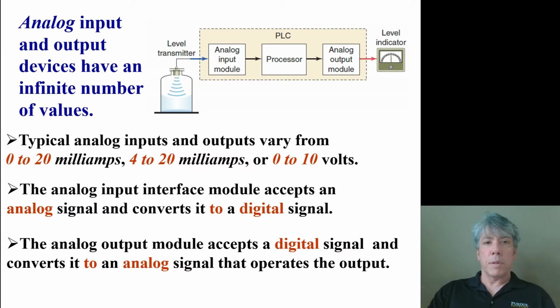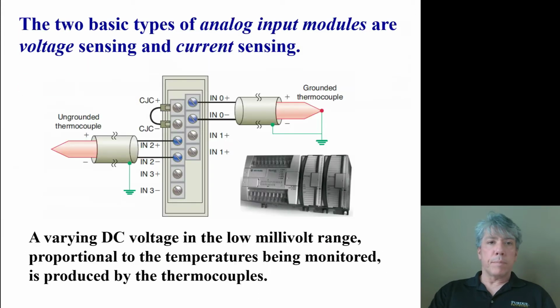It's a computer, essentially. Now we say that they have infinite resolution, but in reality noise effects and things on the electrical signal change the effective resolution that even the analog signal can send, but that's out of the scope of this course. What we're primarily interested in is the resolution that the PLC offers because of this required conversion from the analog to the digital world and from the digital back to the analog world.